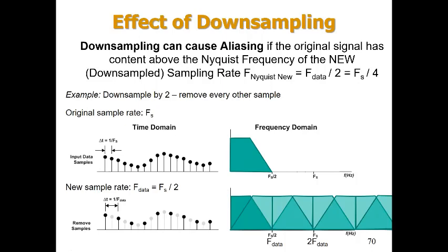That's why when downsampling is typically performed in discrete time systems, it's actually performed as what we call decimation, which is pre-filtering, low-pass filtering the sampled data to the new Nyquist rate for the new data frequency, and then doing the sample throwaways to do the downsampling, so that if there was any signal that could have aliased, it won't be.